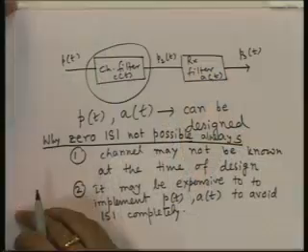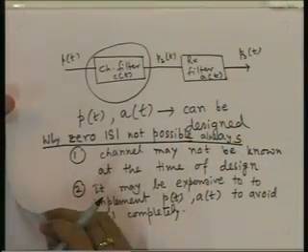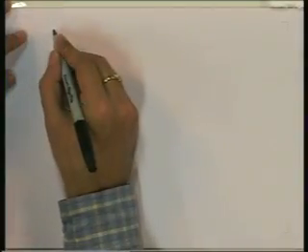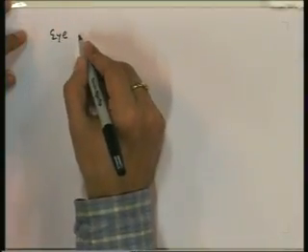If we go in a car or in a train, if you move very fast, the environment around is changing, and as a result the wireless channel is changing. So, in that situation, can we observe how much ISI my communication system is facing? So, the eye diagram is a solution to that.